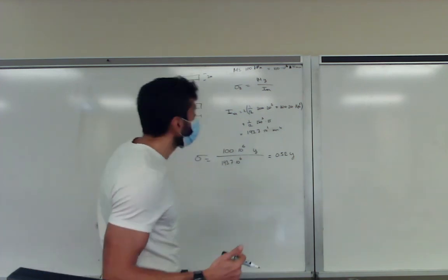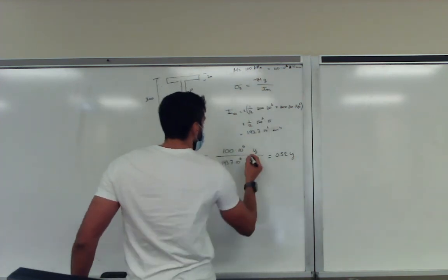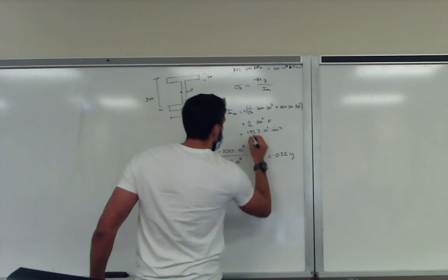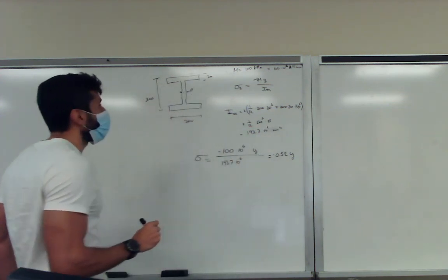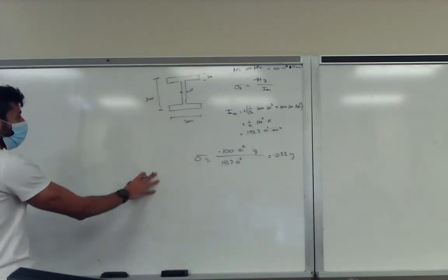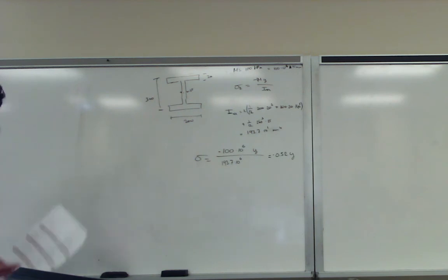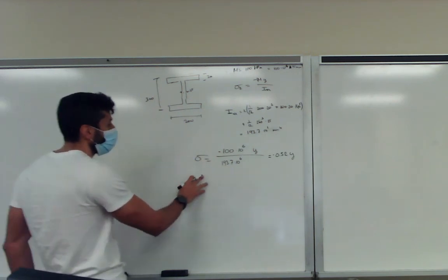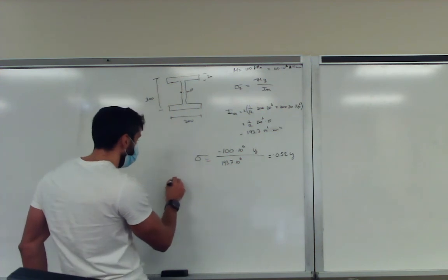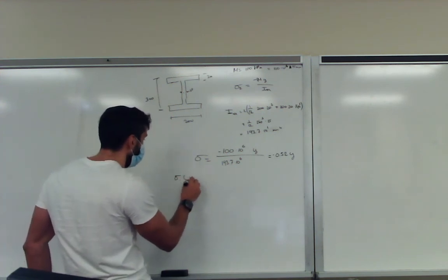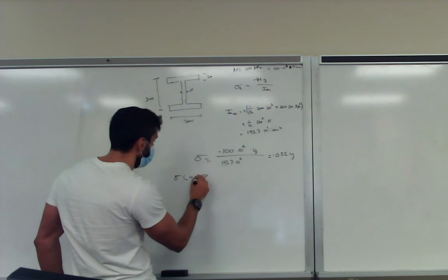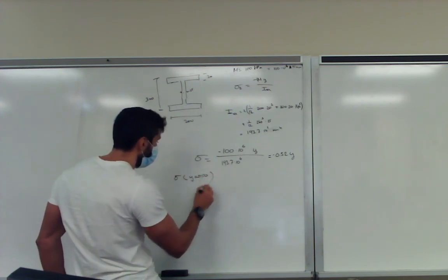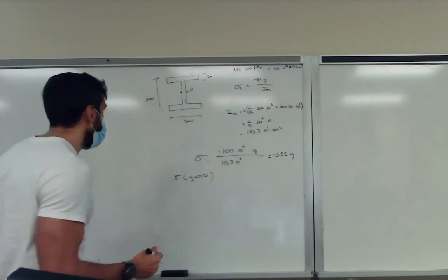It also says a negative bending moment, so we have to apply a negative bending moment. So now we can basically plot it, as I said before. So we evaluate at one location. So we evaluate sigma at y equal to 150 plus minus 150. They're equal, but they're just opposite in sign.